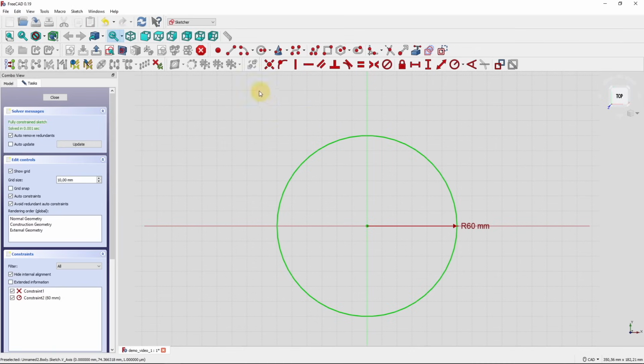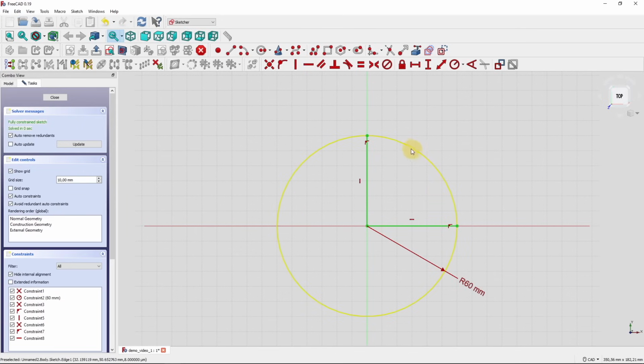In order to do that, I click on the line command here, create a line in the sketch. I start with the first point also here in the origin, and I end on my circle here, and I do exactly the same, starting here on my origin and end here. You will see that there are automatically two constraints created, a vertical constraint here and a horizontal constraint here. Now the sketch is a little bit overdefined because we don't have one single closed shape, but two of them. So therefore we have to trim this quarter.